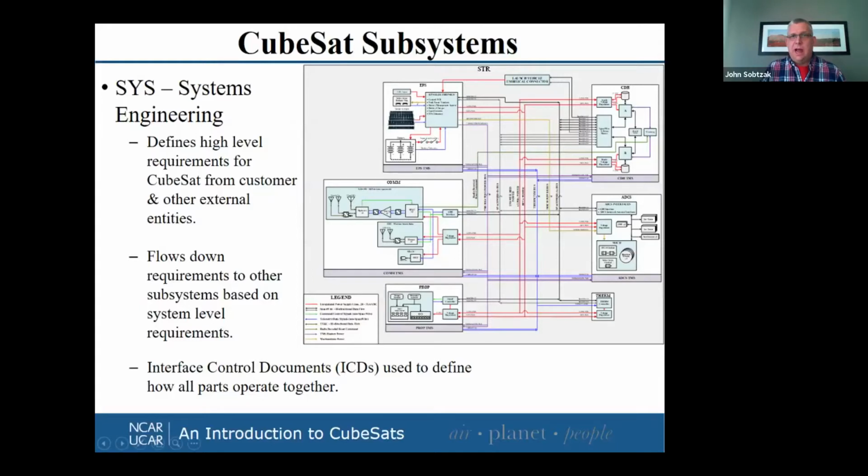And I have the structure surrounding everything because the structure has to hold everything. And then the individual subsystems: the electrical power system has the solar arrays, has the batteries, for example. It has some thermal management system that is controlled by the main thermal subsystem over here. The communication had multiple transmit and receive antennas, and we had a laser communication demonstrator on board. Propulsion, we had some thrusters to help keep us orientated, and some main thrusters to get us out. This particular satellite was designed to go to Mars, so we needed a propulsion system.